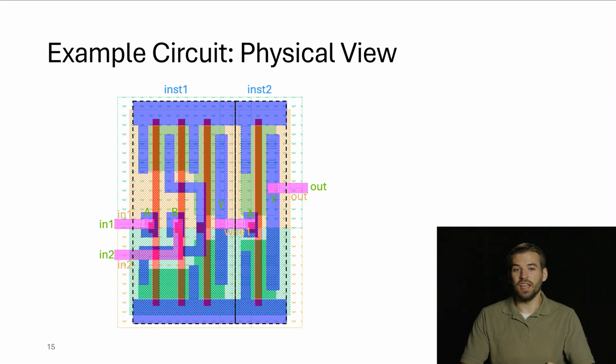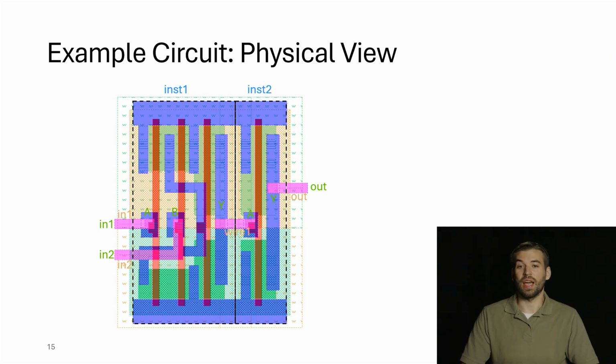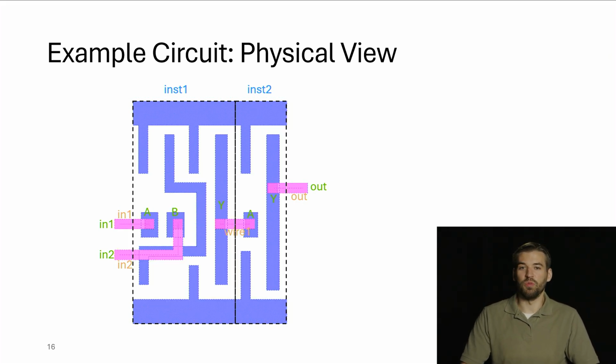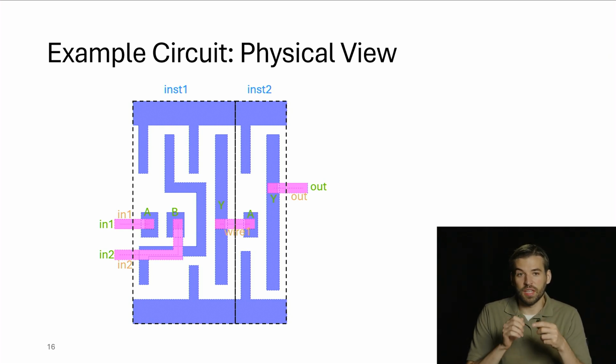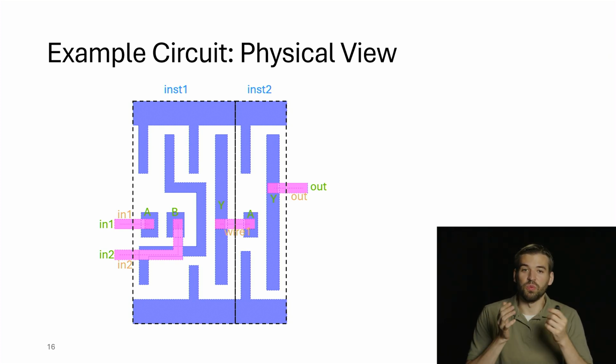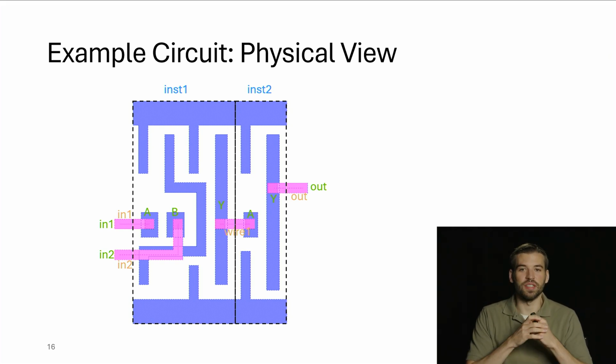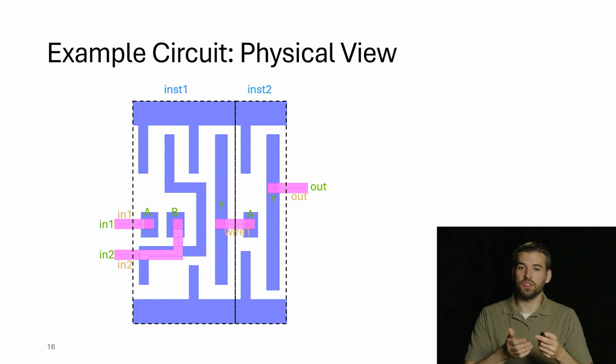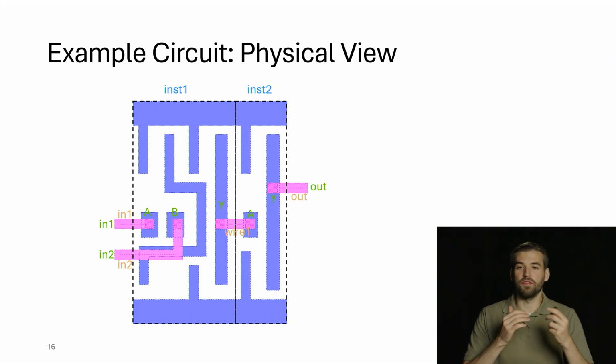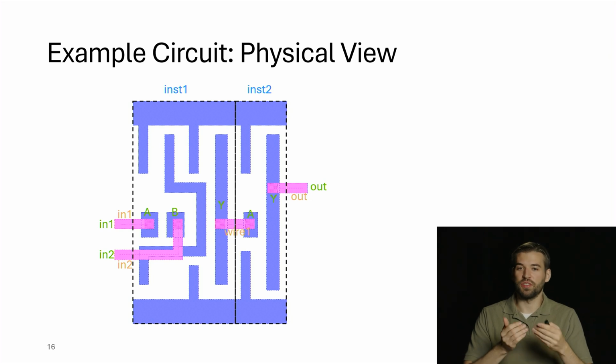Typically, designers and EDA developers don't need to see these deep views inside of the cells. We instead like to work with what are called abstract views. In an abstract view, we take away all of the substrate layers because we aren't concerned with them at this level. The expectation on a designer who draws these masters is that they should fit together nicely and that you shouldn't need to worry about the transistor level details. Those get abstracted out. What we're left with is just the shapes that represent the inputs and outputs of the instances. In our schematic view, these are called terminals, but in this physical view, these shapes are called pins. Pins are the physical shapes that implement the terminals, and pins are always associated with the terminal, so you can't have a pin without a terminal.